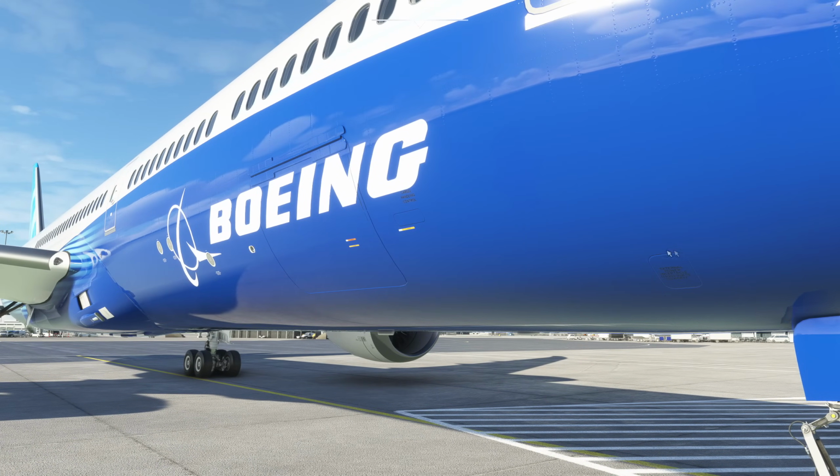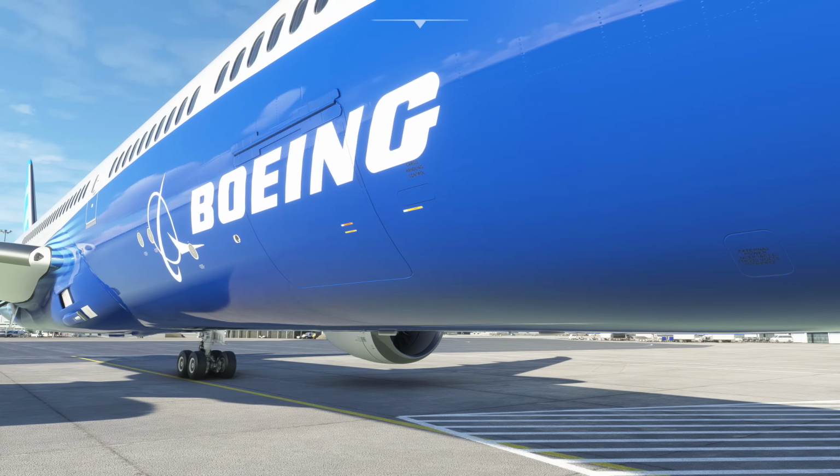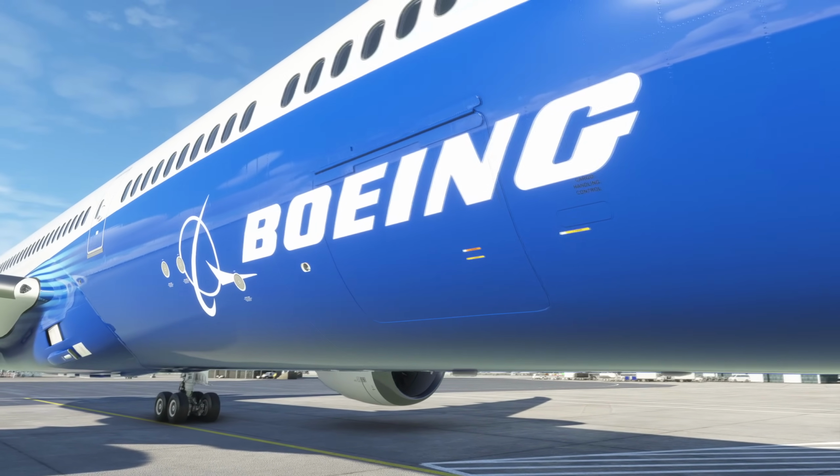This is the ground power unit entrance point. So it takes 2 ground power units through this forward point. The A320 only could use 1 AC ground power. This aircraft can take 3 total, but we only use 2 normally through this front port. There is a third port at the back used in certain situations, which we'll talk about another time.